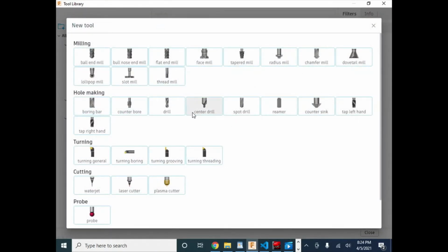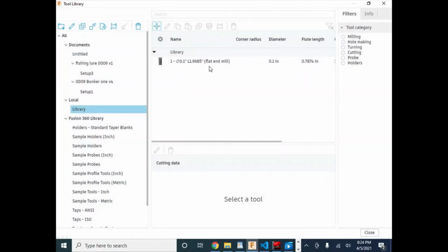If you are doing an engraving feature, just an FYI, something else I just learned was Chamfer Mill is your engraving tool. That's if you have a V-carve bit and you need to do fine detail, you just pick Chamfer Mill and you can put in the parameters there. And the engrave feature in Fusion 360 actually works quite well, but only if you choose chamfer. All right, so we can have a whole discussion about that one.